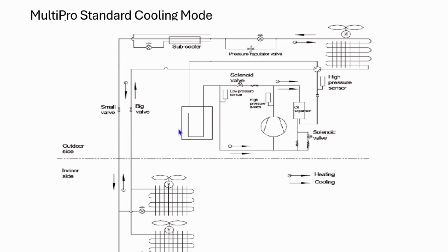When you have a block in refrigerant, let's say your restriction, maybe we close this service valve back and we start backing that liquid up in here. This is what I've seen even in traditional equipment. If I got a restriction, let's say I got 1 indoor coil, 1 outdoor coil, I've got a restriction. When that unit fires up, that head pressure, if you watch your gauge, will go way up. And then all of a sudden it starts falling back down.